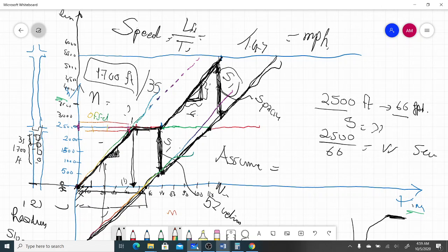Let's say 10, 20, 30, 45 seconds. Let's say just 45 seconds, my offset. And the green time will be 10, 20, 30, 40, 50, 60 seconds of green time. So this is what we call something called an offset and something called the green time. So now I was able to adjust the timing of the signal that will allow the cars not to stop, so to reduce the delay of this fleet of vehicles. And this is one way how we do a design of a traffic signal.